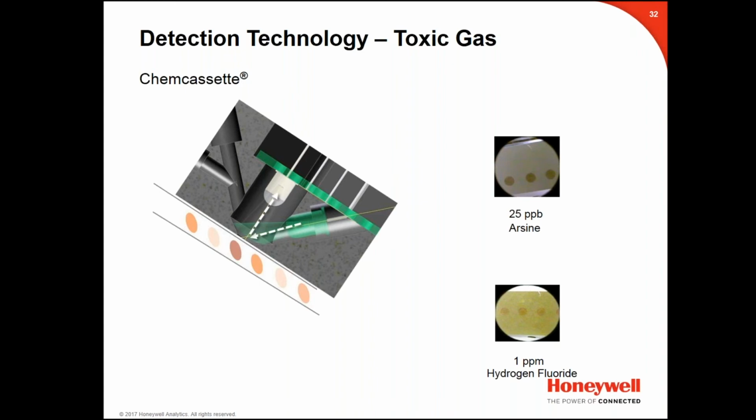The stain intensity that occurs on the paper tape is measured with an electro-optical system which reflects the light from the surface of the substrate to a photocell located at an angle to the light source.